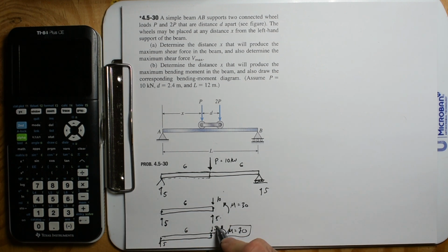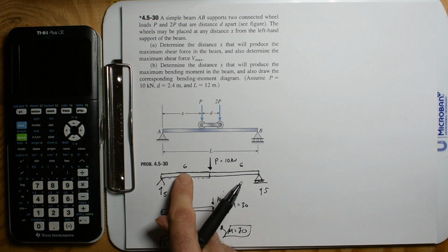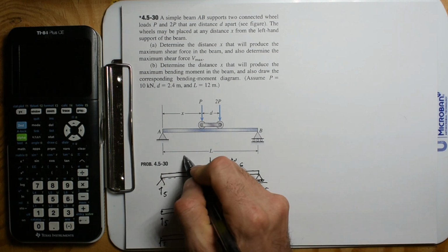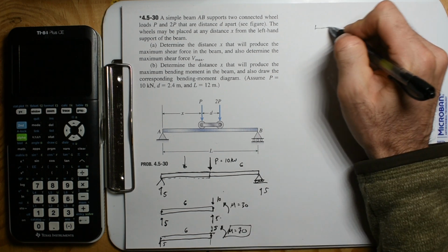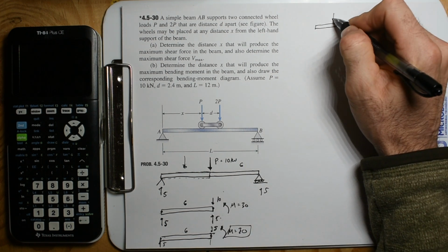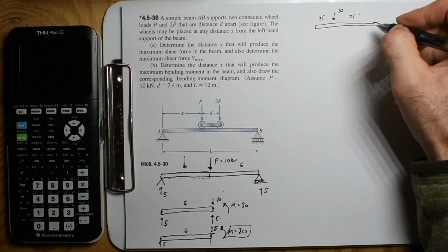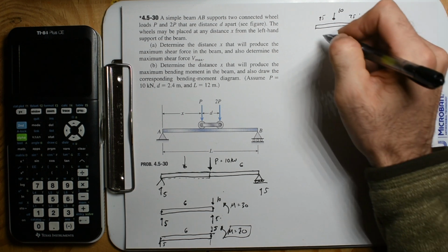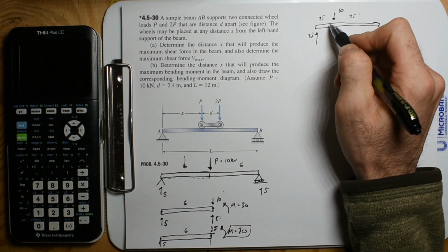Yeah, we had a shear force right here of 5. So along this cut section, this thing is going to want to shear across with a 5 kilonewton load. Now, if we get this load closer, so we're still just going to work with one load, and we put it at a quarter of the distance. So let's draw that. If we put that load at a quarter of the distance, this is 25%, this is 75%, this is 10. So you're going to have 2.5 right there, and then 7.5 right there.